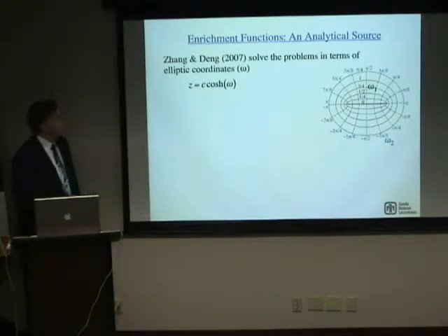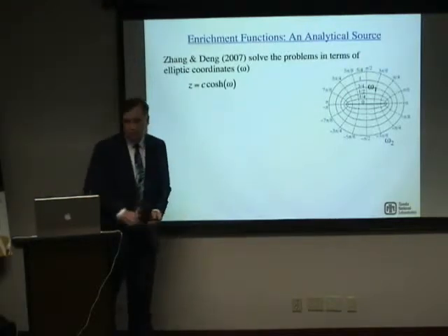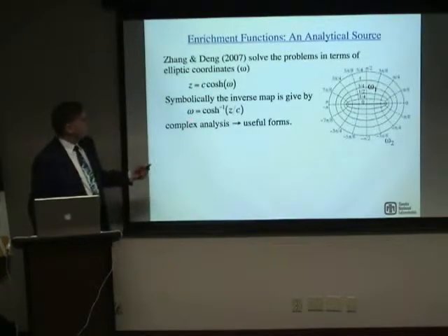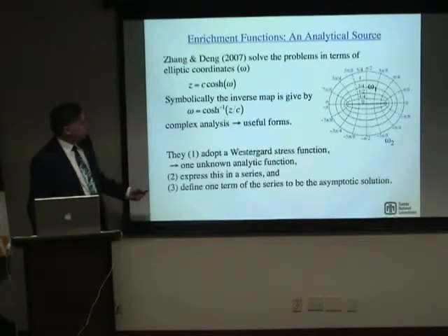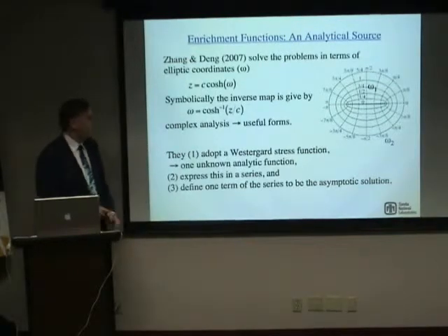And as such, you can relate the coordinates of a point in the domain as a complex variable in terms of its elliptic coordinates in the domain. And with a little bit of screaming and gnashing of teeth, you can work your way backwards to have the inverse relationship, which you're going to need if you're going to do numerical integrations on basis functions that have products from this.